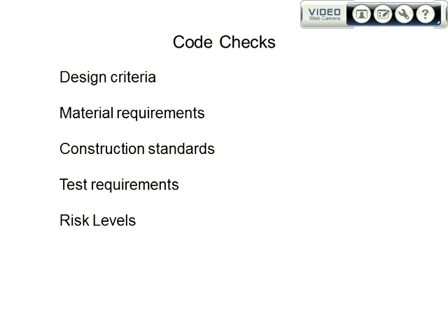That should be a straightforward check. And then the material requirements, you need to think, what are the key material requirements that we've got to meet? To be honest, the key issue here is, is the material that the pipeline's been constructed of acceptable for transporting CO2?